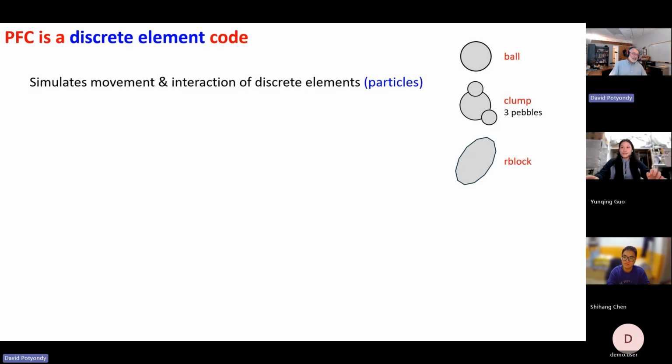So it has a single centroid, it has 6 degrees of freedom, etc. So if we wanted to model a bowling pin, we could have 5,000 overlapping little things that are one big rigid thing. That's called a clump. So it's a way of making a generalized shape, but the shape has bumpiness to it, right?